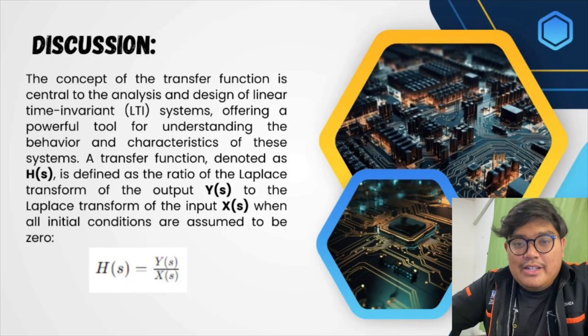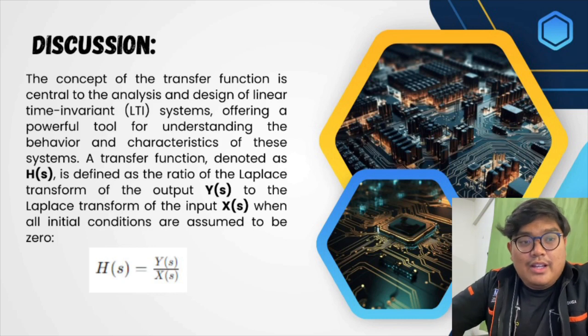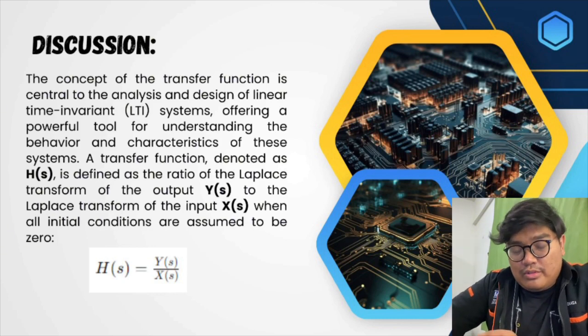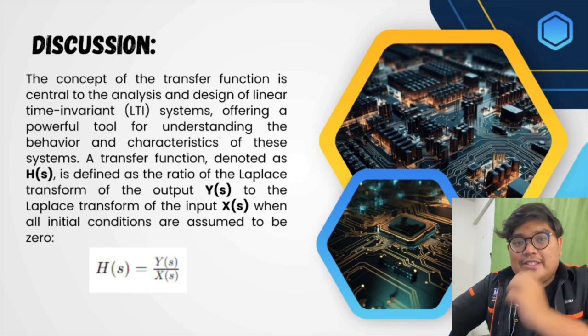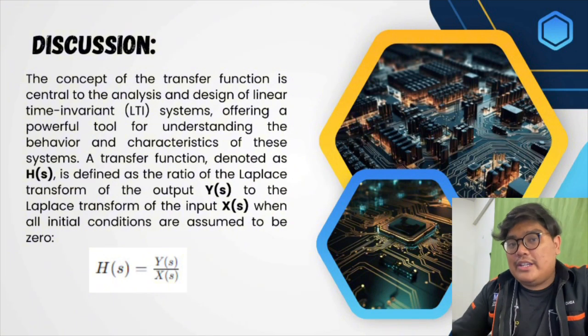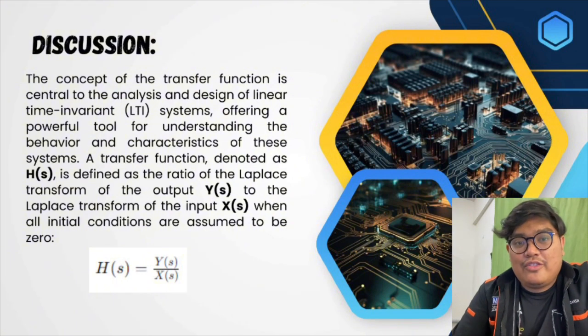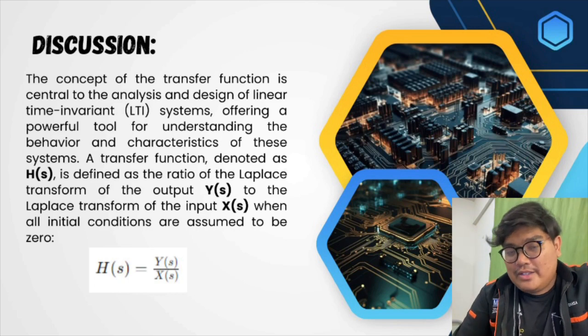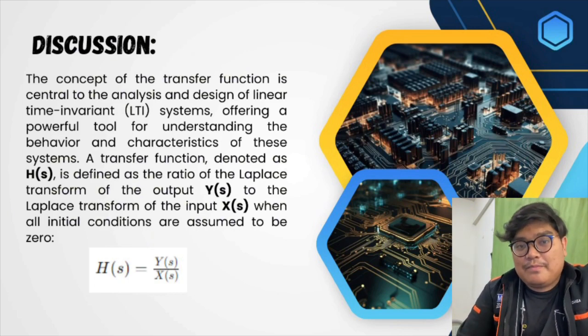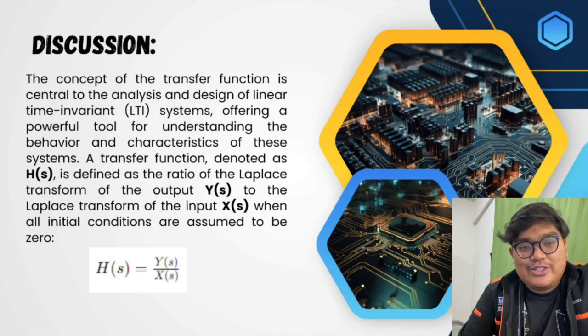Assalamualaikum, my name is Ahmad Daniel. I'm the last presenter of this group. I'm going to explain and discuss transfer function. The concept of transfer function is central to the analysis and design of linear time-invariant (LTI) systems, offering a powerful tool for understanding the behavior and characteristics of these systems. A transfer function, denoted as H(s), is defined as the ratio of the Laplace transform of the output Y(s) to the Laplace transform of the input X(s) when all initial conditions are assumed to be zero.